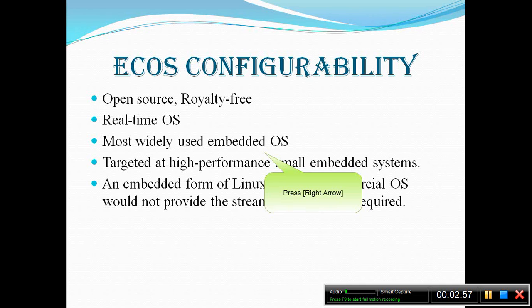For example, many real-time operating systems support task switching, concurrency controls and a variety of priority scheduling mechanisms. A relatively simple embedded system would not need all the features. So the challenge is to provide an efficient, user-friendly mechanism for configuring selected components and for enabling and disabling particular features within components. The eCos configuration tool, which runs on Windows or Linux, is used to configure an eCos package to run on a target embedded system.